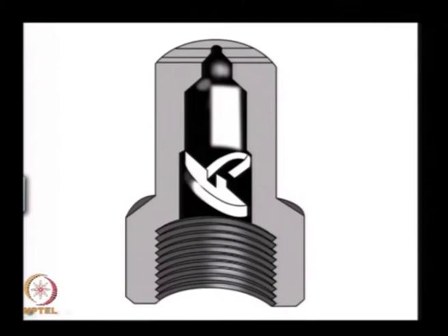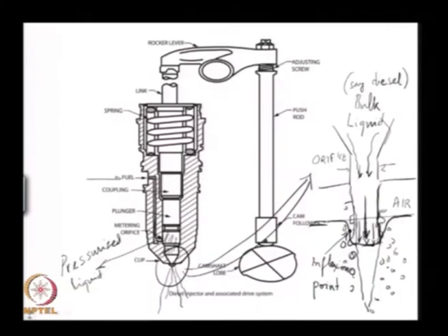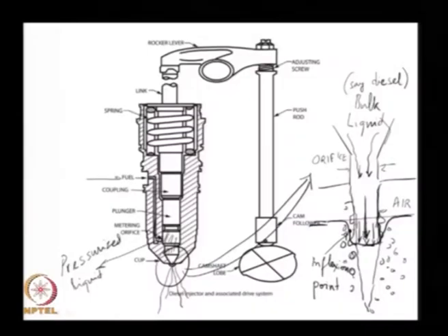In the previous diesel injector design, if I increase the mass flow rate for the same orifice diameter, I have essentially increased the velocity of the liquid coming out, which means I have increased the nature of the instability at the inflection point. I am likely to get smaller drops.